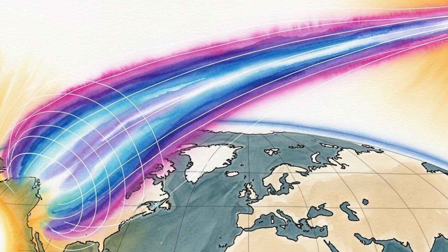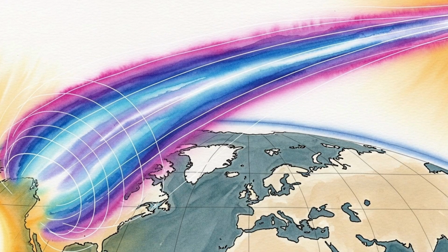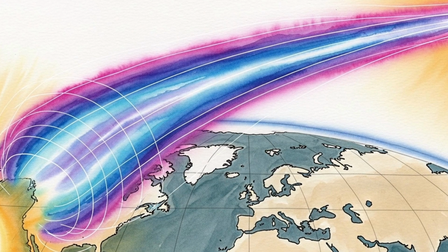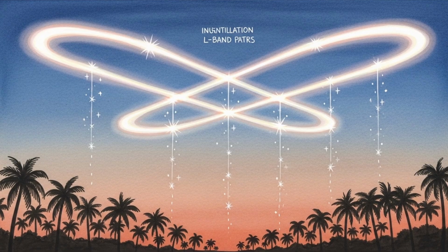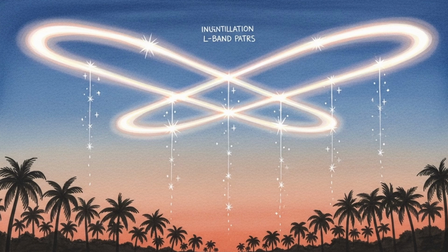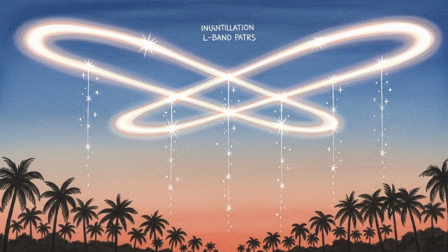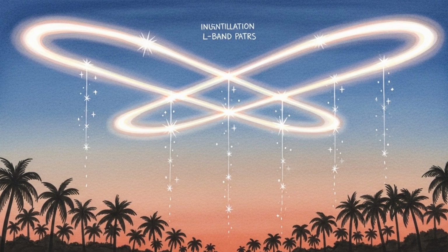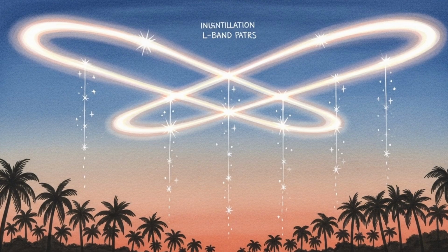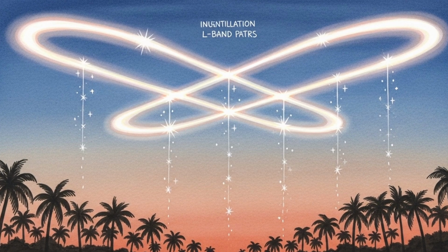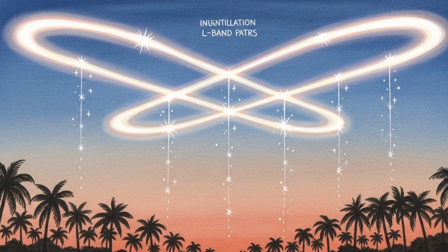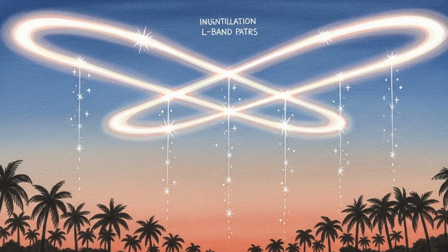Long lines that run parallel to the expected electric field direction are reviewed. If alternatives exist, flows are rerouted to shorten effective exposure. Spare transformer cooling fans and pumps are tested. Staff levels are increased, and control rooms review the storm checklist.